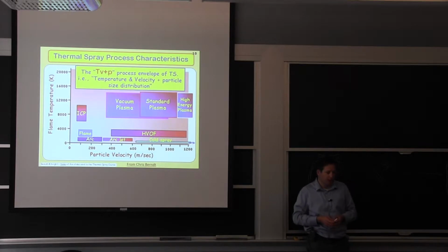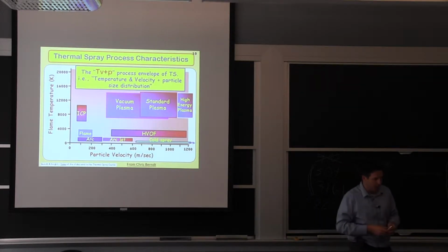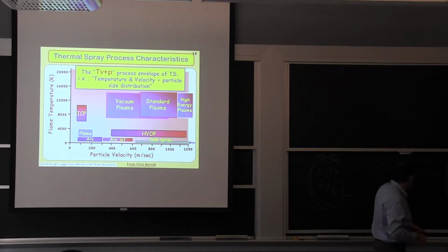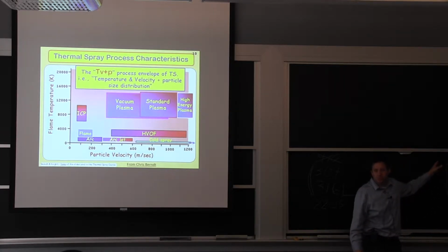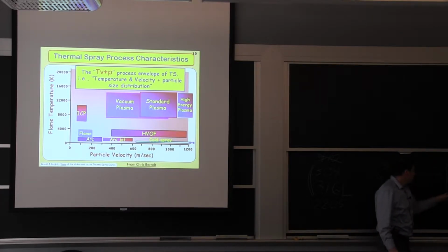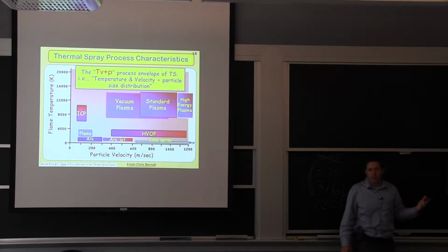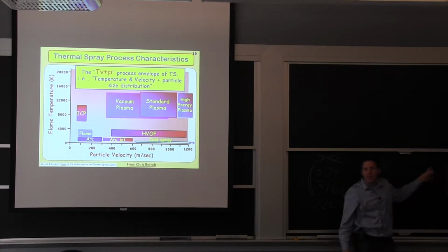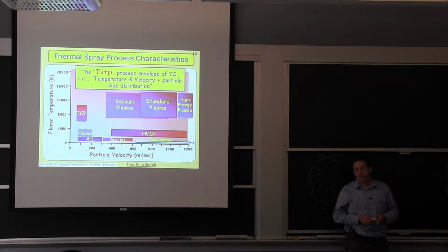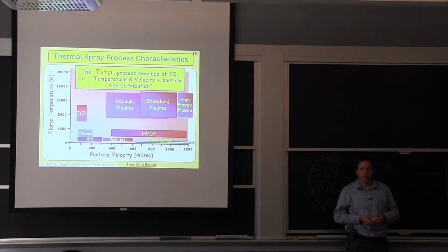You can do tungsten carbide if you want. The problem, as you can see here, as I'm building up this layer, I keep adding residual stresses. So I'm only going to be able to do, say, 1 millimeter or so before I start debonding that interface, because I keep adding and adding residual stresses. The only option is to heat it up and do a relief of residual stresses and then continue, but then all of a sudden it becomes more expensive.